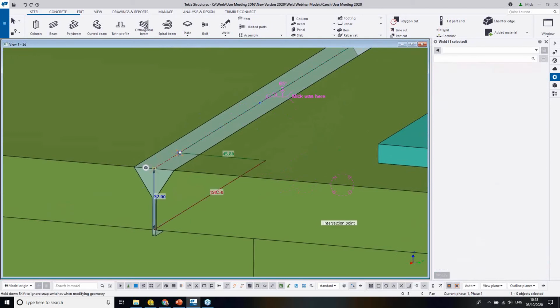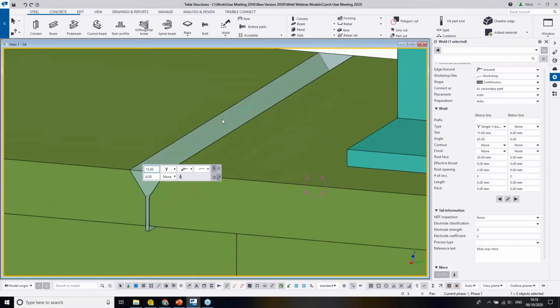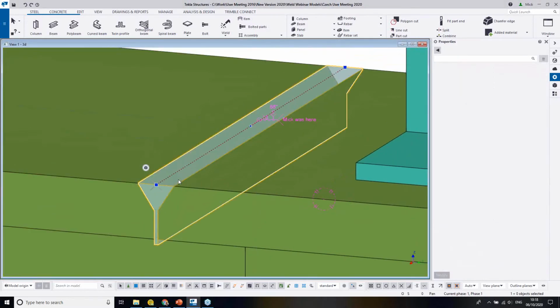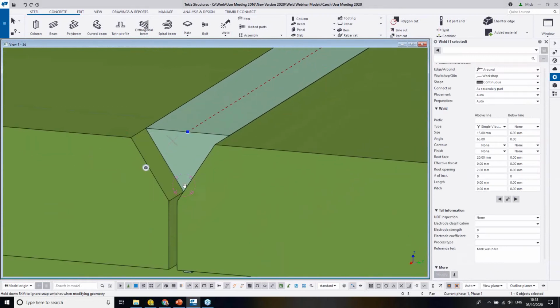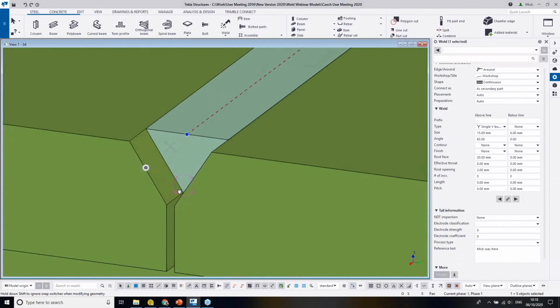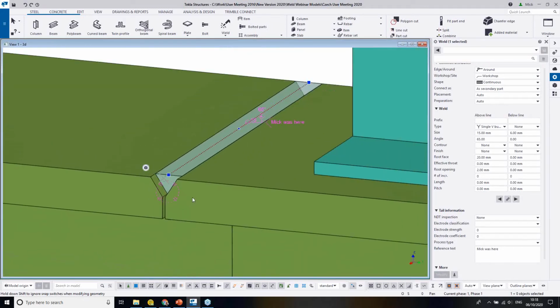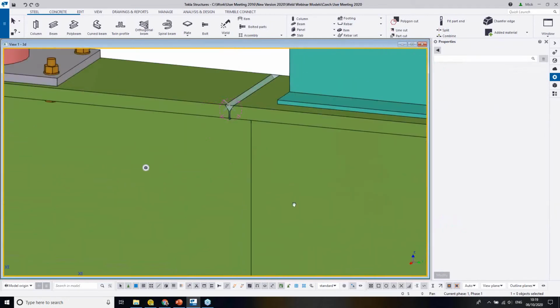And if I pick this weld up and drag it out, like so, pick that piece up, there we pick on that weld, there we are. And if I just drag it in slightly, you'll see, look, the piece has been prepared for the weld. So the part is automatically cut within the Tekla model. So every weld you put in there, actually now you can define the weld preparation automatically from it.